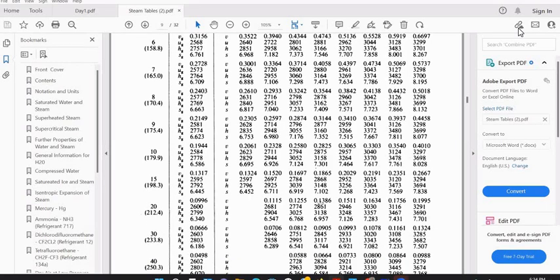Now for 350, you should know the H values. Here 360, H value 3138 and then 31. So I will write all these here. Interpolation. Now you have to go for the mathematical interpolation here.